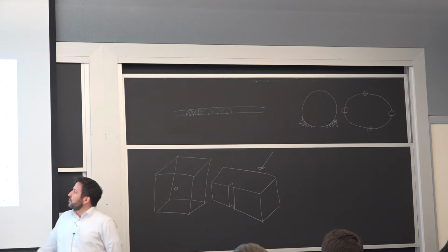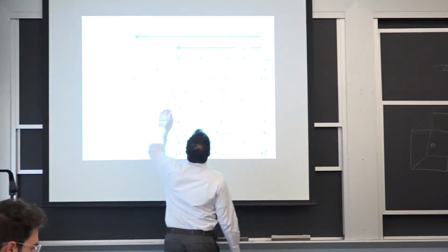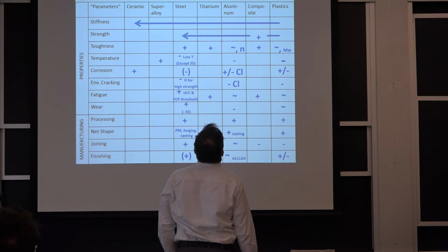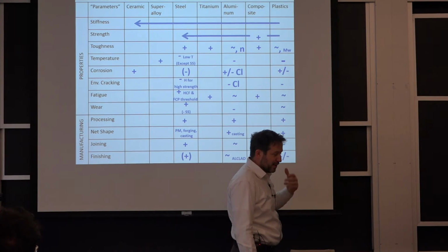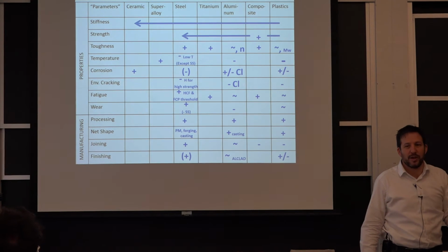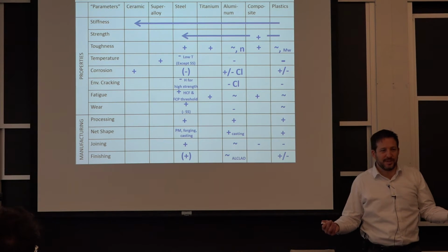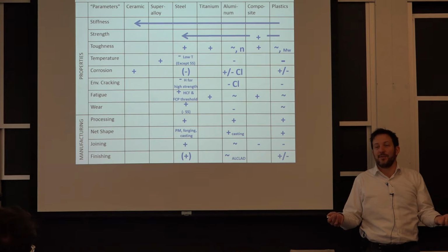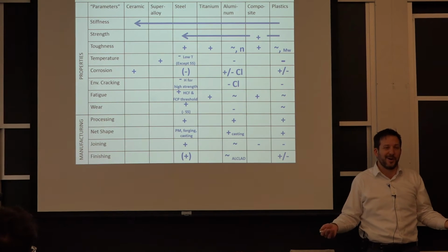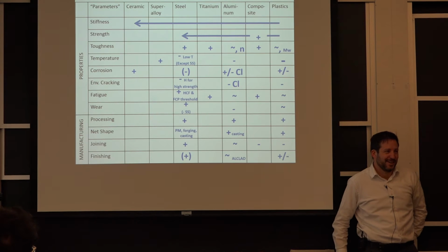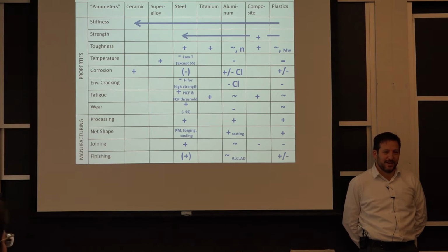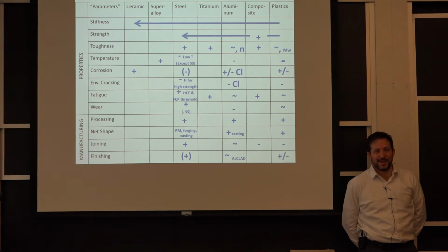So in terms of the pluses and advantages, that's really a disadvantage of steel, and aluminum is the opposite. When we were talking about the aircraft wings, aluminum was the opposite. If you heat it up, it softens very easily. So even a structural fire, if you were to make a building out of aluminum, would really be a problem. You can literally cook a small fire and everything becomes soft and melts, while with structural steel you would not have a problem. So the day you want to make a building out of aluminum, let's talk about that first.